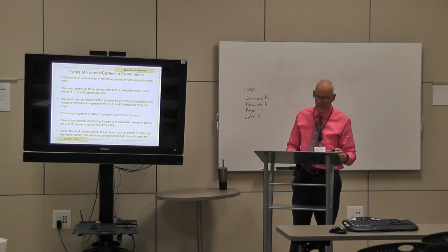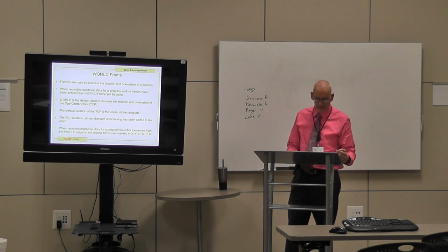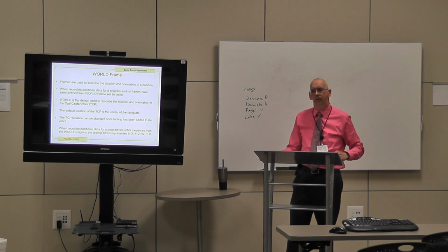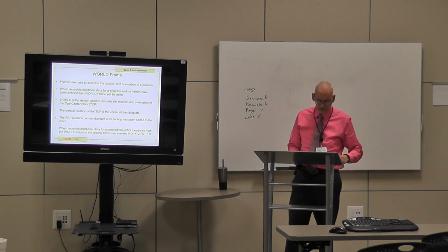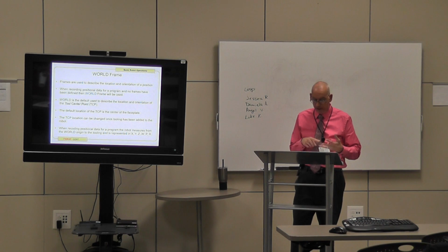All right, next, world frame. We've already discussed world frame when we dealt with learning our coordinate systems, so this is a review. Frames are used to describe the location and the orientation of the position. We discussed that when recording the positional data for a program, and no frame